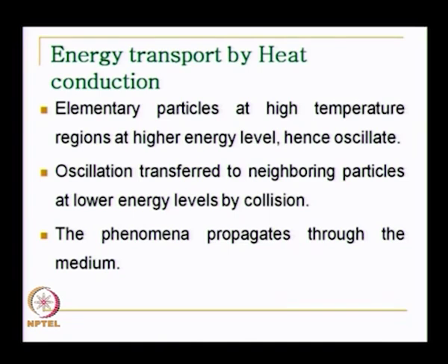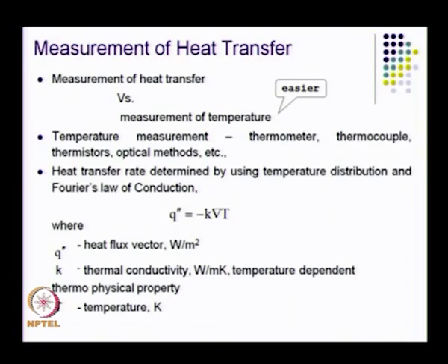the energy carried by the particles with a higher temperature is more compared to the energy carried by the particles with a lower temperature. Therefore there is a net positive transfer of energy in the direction of decreasing temperature. That is a mechanism of conduction which can be easily explained in the case of gases. You can also extend this to liquids. For solids it is more difficult, valence electrons and all those things will come into the picture, okay. So if you look at energy transport by heat conduction, oscillation is transferred to neighboring particles, and the phenomenon propagates through the medium, right.